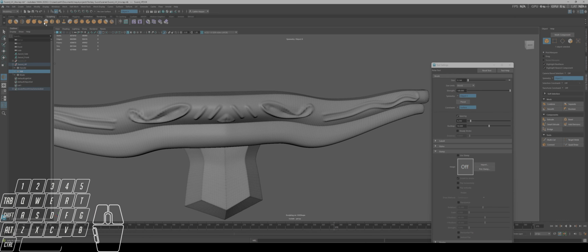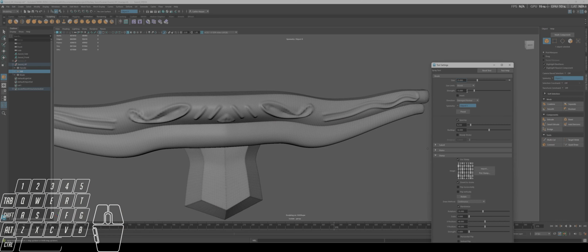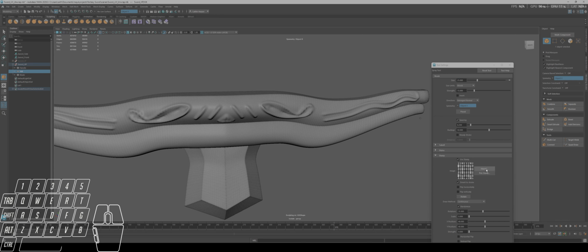Another thing that I'm actually going to use, I'm going to find this stamp repeatedly along a pattern. There we are. And what I found with this one, if I reset my tool, I brought the size and the strength quite low down, but what I'm going to use with this is actually make these kind of dappled effects, make it look a little bit roughly hewn. So all I'm going to do is it's got stamp on by default. I'm quite happy with this checkerboard stamp, but if you want to choose one, there are a bunch of defaults in here. If we go to pick stamp, we can choose from some of these. You might go for something a little bit different. You can even import a stamp, but I'll talk a little bit more in detail about that as we go through.